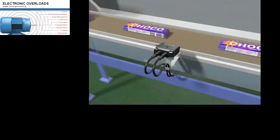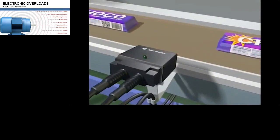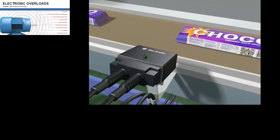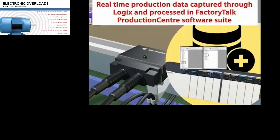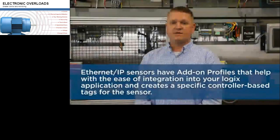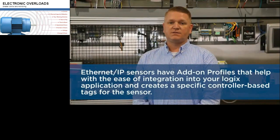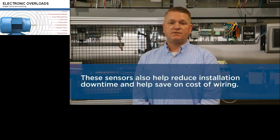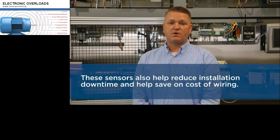In this application scenario, a range of smart sensors are used for production tracking and historical trace requirements. For item level tracking, a high-speed code reader captures barcode or 2D code data and communicates this over the Ethernet IP network. The Ethernet IP sensors have add-on profiles that help with the ease of integration into your Logix application and create specific controller-based tags for the sensor. These sensors also help reduce installation downtime and save on cost of wiring.